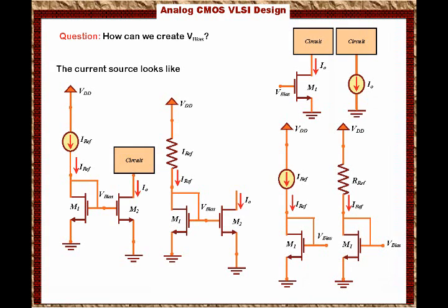That biases the circuit. We call this circuit the current mirror. Why do we call it the current mirror? Because these two transistors are a reflection of each other, so they are almost like the mirror image of each other, right? Basically, I out is the mirror image of I reference, and note that the voltage VGS1 is the same as VGS2.